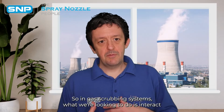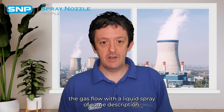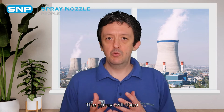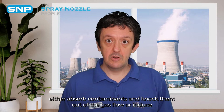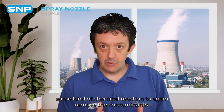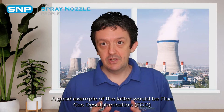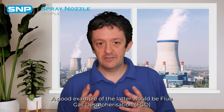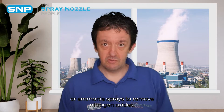So in gas scrubbing systems, what we're looking to do is interact a gas flow with a liquid spray of some description. The spray will then either absorb contaminants and knock them out of the gas flow, or will induce some kind of chemical reaction to again remove the contaminants. A good example of the latter would be flue gas desulfurization or ammonia sprays to remove nitrogen oxides.